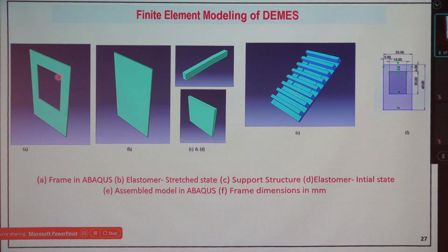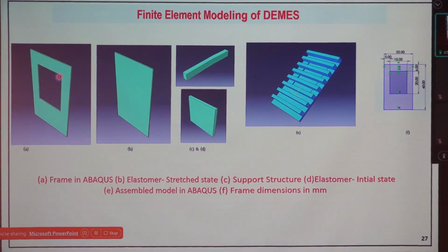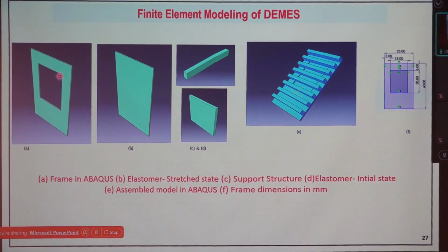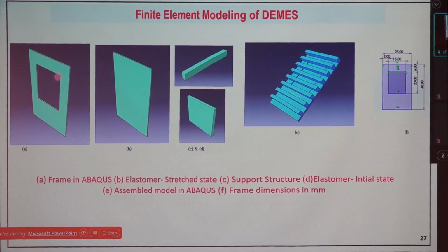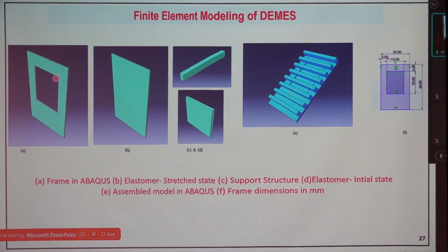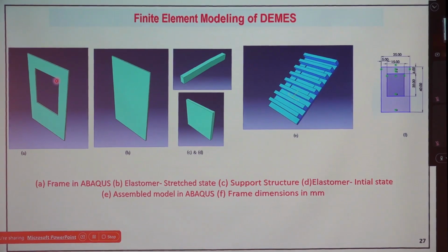Okay, so we supply the shear modulus. In a hyperelastic model, basically C1 we have to define. The energy is C1 times (I1 minus 3), where C1 is mu by 2, mu being the shear modulus. We know the shear modulus of the dielectric membrane, so we put the value of C1 there.